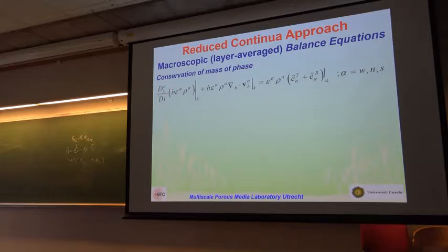Yeah, but I multiplied by B. That's why I need B explicitly out there. Because B changes with time, B changes with space. If I do that, then I bury that dependency in the material per surface. I don't want to do that. Well, the density per unit of surface area can change for whatever reason. Yeah, but I'd rather break it into B times water density, which is known, and I can assume it to be constant. For me, this is advantageous because rho I can always cross out. But as soon as we say mass of water per surface area, even for incompressible water, I cannot cross it out.